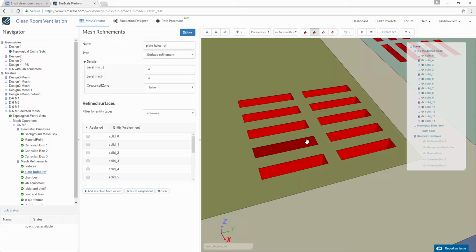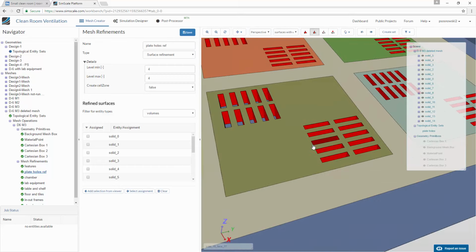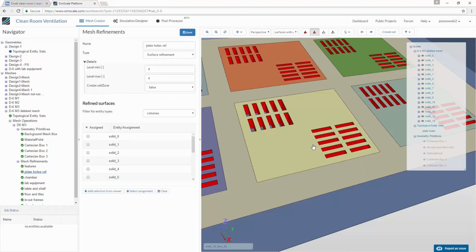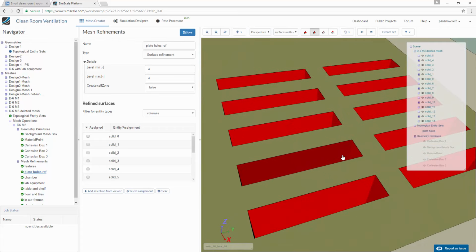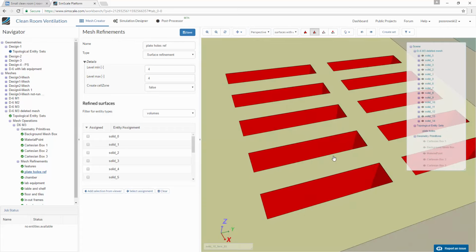Whenever I think of a mesh for those small details, I remember the picture of Mona Lisa. If I put this picture in the resolution of 32 pixels by 32 pixels, obviously I will not see any of the details. Sometimes we could use a bigger pixel to represent a big chunk of the same color of a painting. But at the same time, when we are talking about small elements, we need a finer resolution. And that's exactly what we are doing when increasing the mesh quality at those faces.